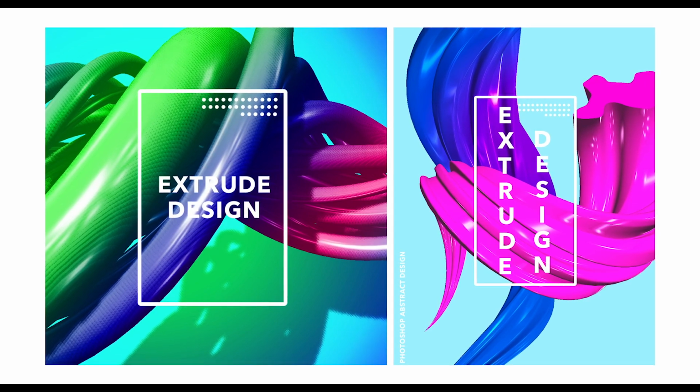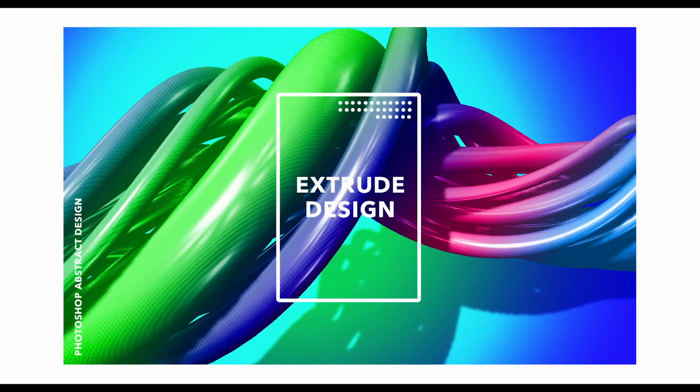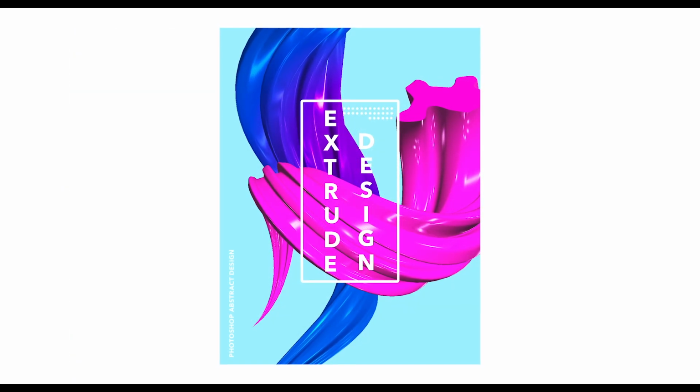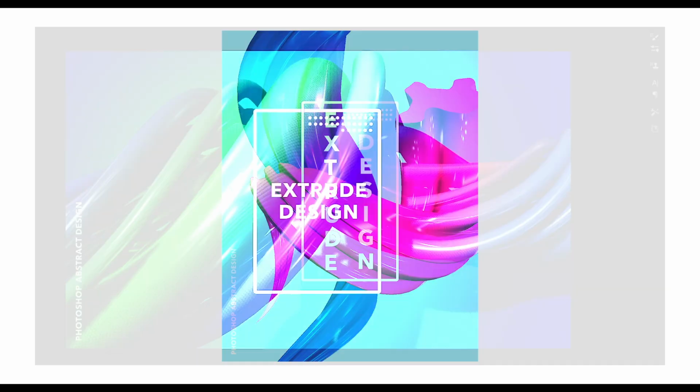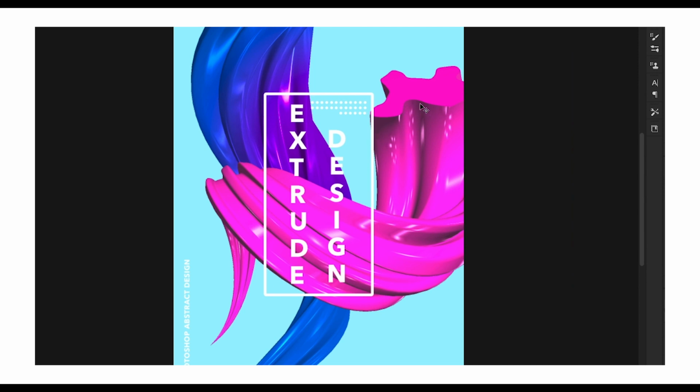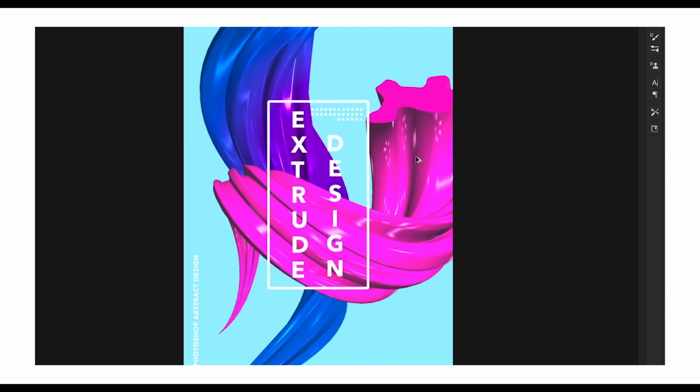Today we'll be looking at how you can create Extrude Abstract design using Photoshop. We'll be using the 3D extrusion option to create some amazing design. We'll be creating two different designs. The first one will be this. We'll be using the circle ellipse tool to create this design, and for the second design we're going to use some shapes. So we're going to draw it out using the pen tool and then use the 3D extrusion options and some of the attributes to create this design.